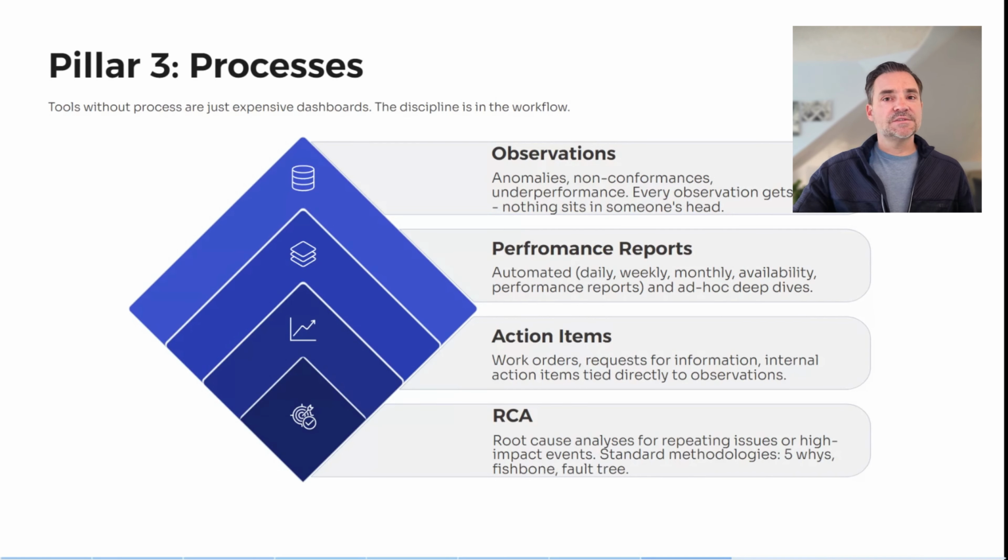This could be someone has observed something, you're doing a daily check, you observe you were not meeting set point, or one battery is running hotter than another, or it looks like the power balancing is not right. You need a way to record it. So being able to record observations is super important. These observations could be alarms that are triggered by your data platform. This observation could be a daily report that's sent to you with some KPIs. So that's the layer of things that you collect.